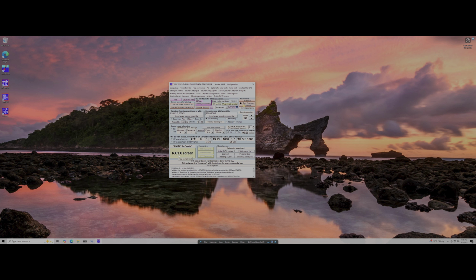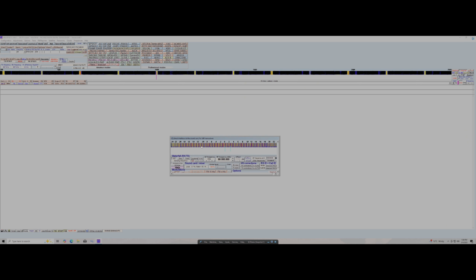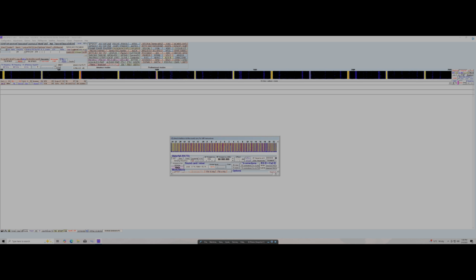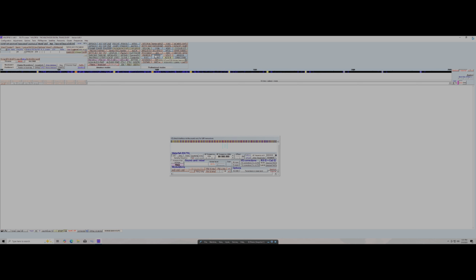But if we go to our receive transmit screen, then you can see there's tons of little goodies all over the place here. Here's our IQ Direct. Here's how we would control our RTL-SDR with all sorts of different modulations. We can do AM, upper sideband, lower sideband, different FM bandwidths you can select, all sorts of stuff. And then here's all the modes you can choose from. So I was primarily using EPIRB mode, which is for ELT, distress beacons and things like that.